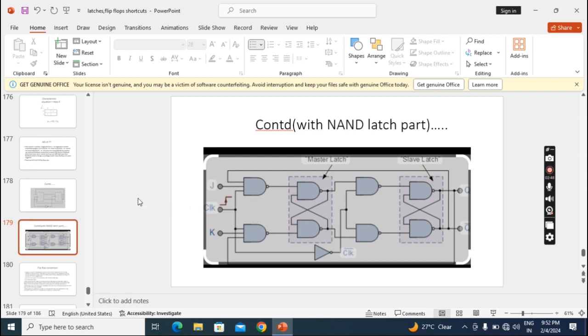Okay, so this master slave flip flop is called a pulse triggered flip flop, because during positive the master is working, during negative the slave is working, and together in total pulse the whole circuit is working. So the final output becomes the slave output and the input becomes the master input. Okay, right.